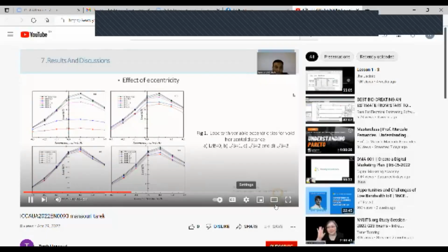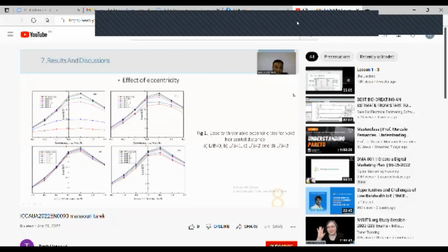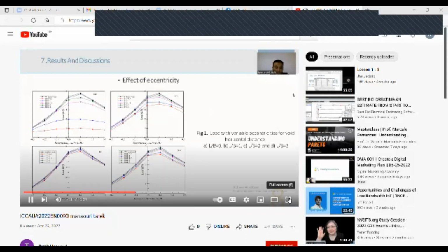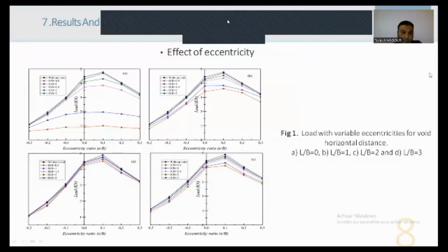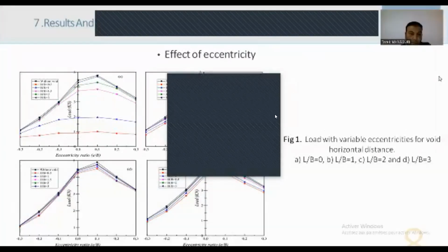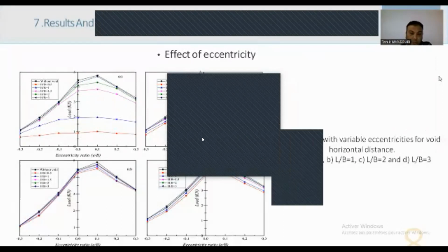A reversal of the footing was observed, which occurred and gradually reduced the bearing capacity value. Furthermore, the ultimate bearing capacity for a negative eccentric load is inferior to a positive one. This signifies that the failure region under a positive eccentric loading is greater than that under a negative one. The gradual displacements shifted to the slope leaning, and a non-symmetrical failure mechanism was observed.